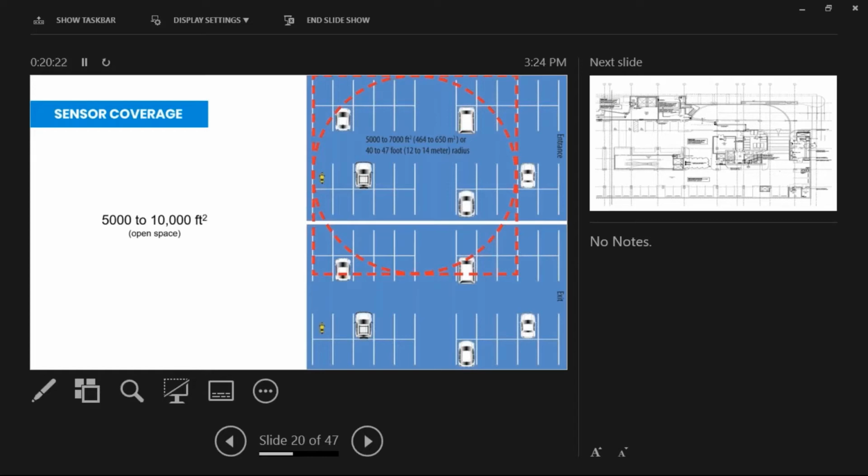Simply because in an underground parking garage, you're not monitoring to workplace health and safety exposure limits. You're trying to balance exposure limits with energy saving when it comes to underground parking, because ASHRAE recommends, and most building codes state, that the only acceptable method to operate your ventilation intermittently in an enclosed space where there's a possibility of vehicle exhaust is to operate the ventilation with controls being CO and NO2 sensors.